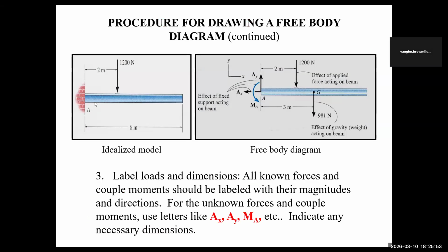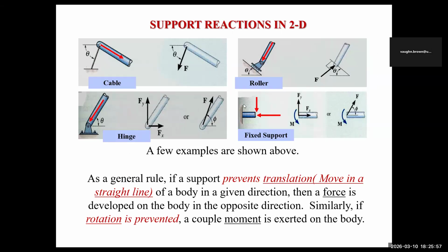Look, you see how we know this is pinned to here, and similarly, this is pinned here. So we know that there are reactions going on both on this body here. One is going out, one is going out. And look, they are going in opposite directions here. So those are the forces being anchored on this. Therefore, your reaction must go opposite to this. The black shows you the reaction. Red shows you the force that is applied to it. Black shows you the reactions.